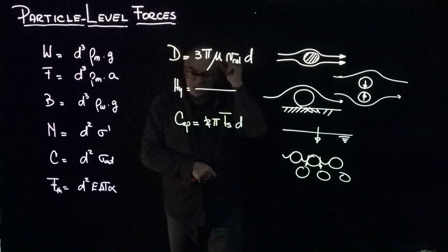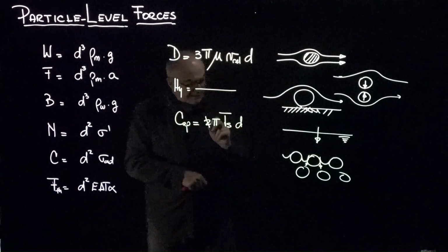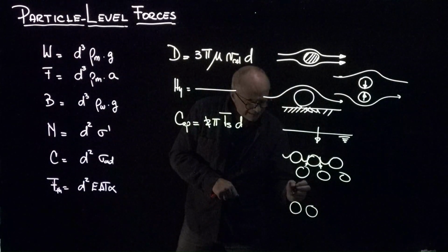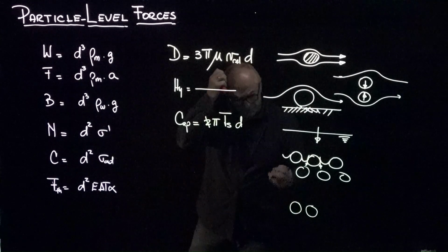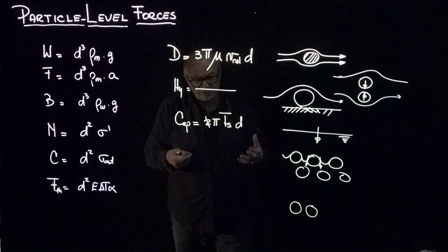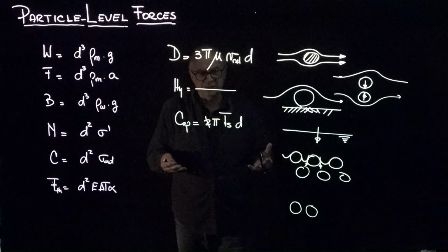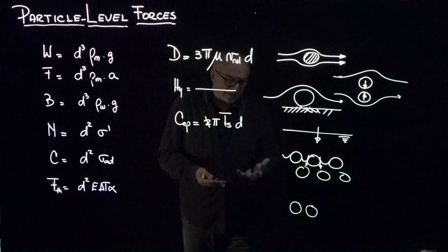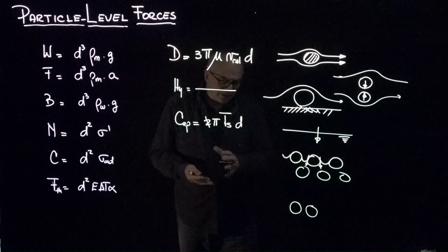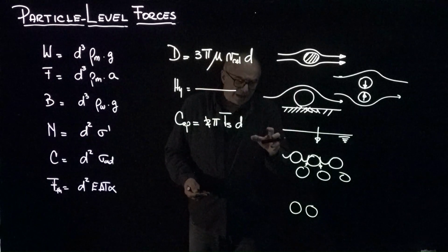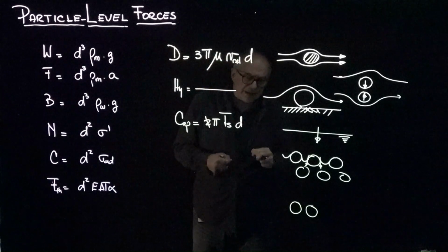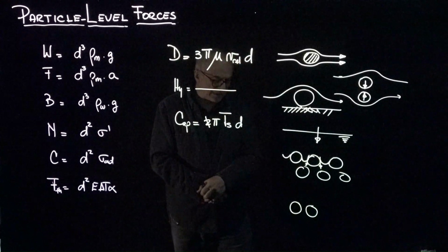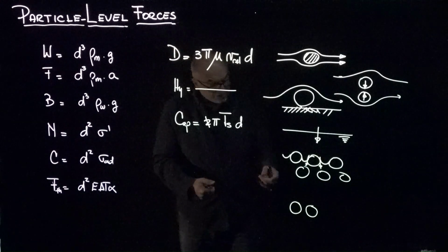There are other situations that may emerge, and sometimes particles get greasy. They're hydrophobic, and we can purposely do that. For example, we do that to do mineral separation in the mining industry. We make the particles hydrophobic, and then we bubble air, and because particles hate the water, as soon as they see an air bubble, they will go and grab the air bubble and will float with it, a technique called flotation for mineral separation. So the same will happen here.